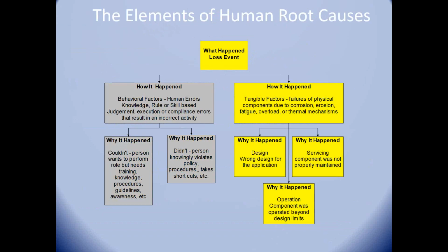And one of the things that the company did quite often, that we had to follow suit with, was you would build a plant that was designed for a certain rate per hour, rate per day. And after that plant ran for a year and a half, they wanted to add 15 or 20% to the rate. So we'd speed things up, add a little bit of equipment. Well, most of the facilities in that company ran at 50 to 100% over what they were designed to do. We operated beyond their design limits. And again, maintenance cost was going up. Failure numbers were going up because we were doing that. Yes, we were getting more rate out of the equipment, but lots of equipment wear and lots of equipment downtime. So we operated beyond its design limits.